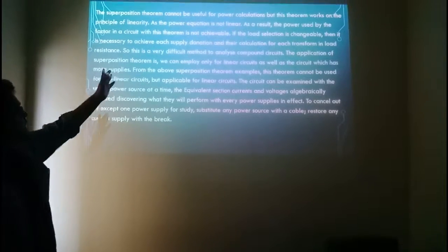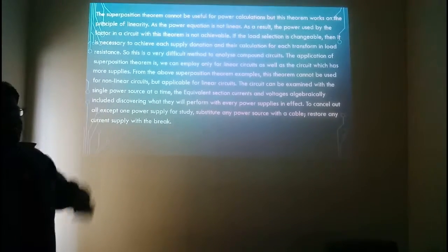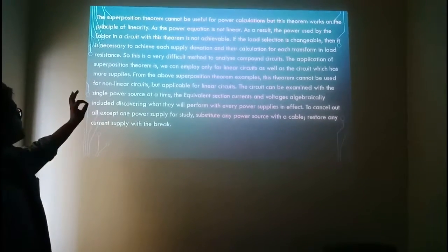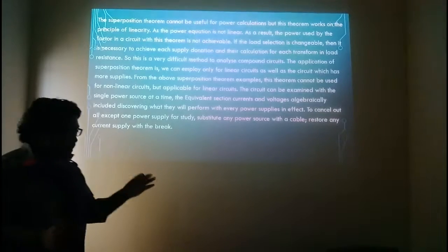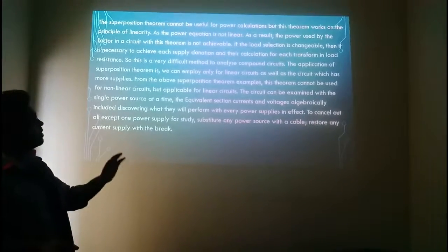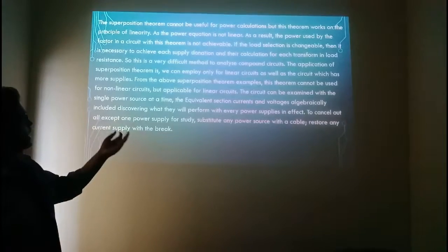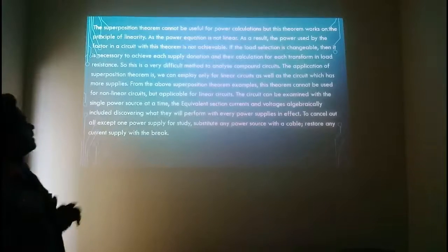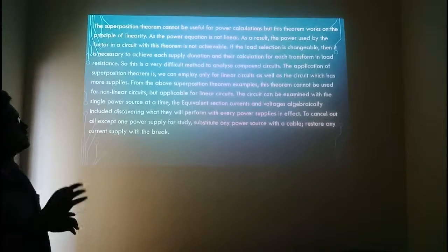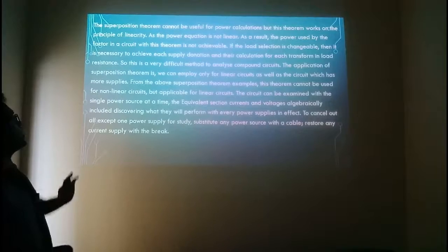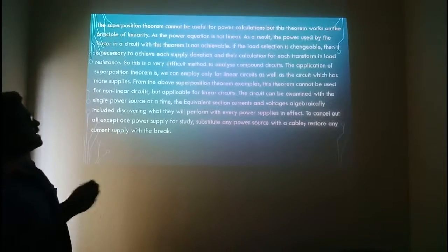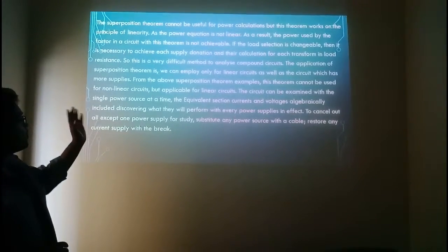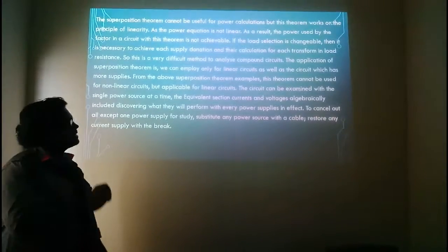Now, can the superposition theorem be useful for power calculations? As I said before, this theorem works on the principle of linearity. As the power equation is not linear, as a result, for the power used by a component in the circuit, this theorem is not applicable. If the load is changeable, then it is necessary to calculate each supply's contribution for each change in load resistance. So this is a very difficult method to analyze complex circuits.